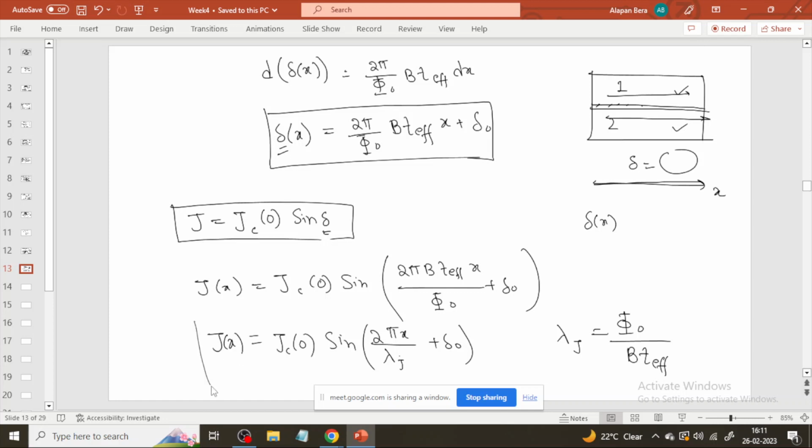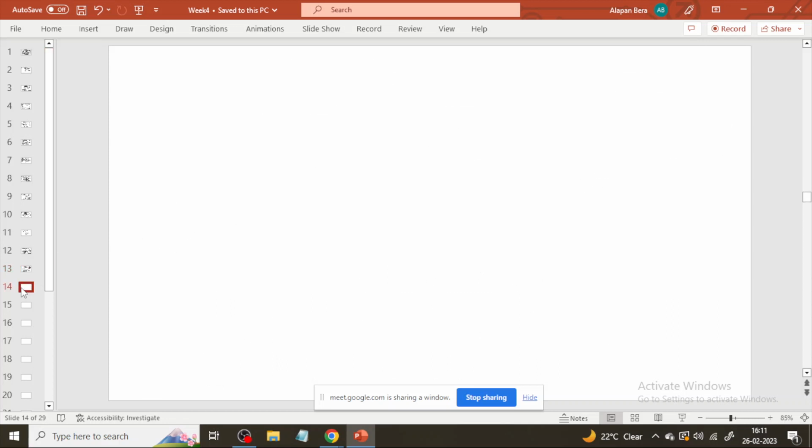Jx. But till now we have only got the current density along the Josephson junction, how it gets modified in the presence of a magnetic field. So if we apply a voltage from here and also measure, then we have derived the equation for how much the current density changes in the presence of a magnetic field. But we have not yet derived how much the current changes. And to derive that, we have to integrate this equation over the surface S.